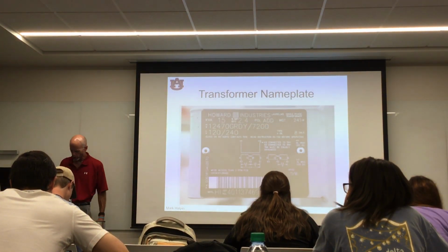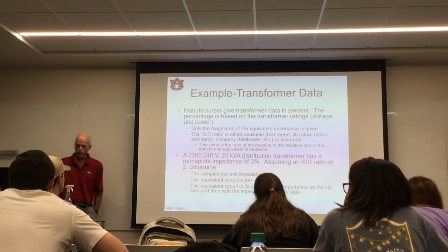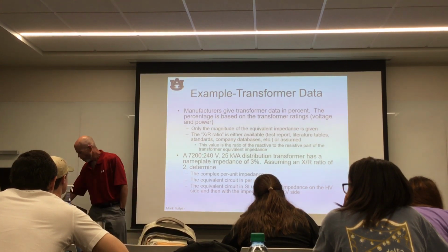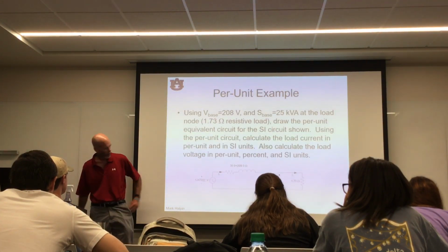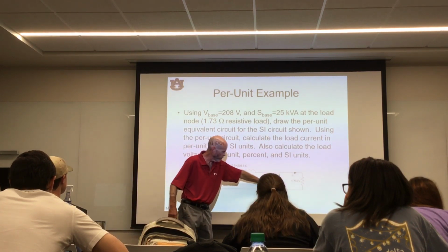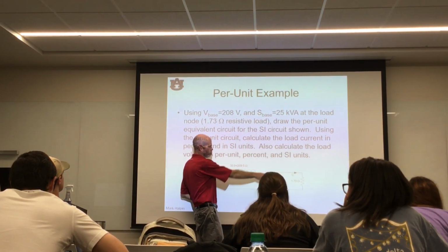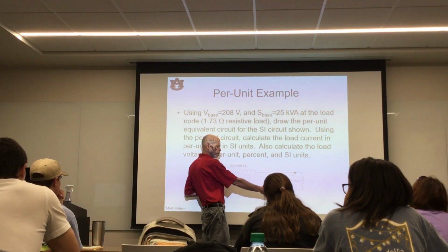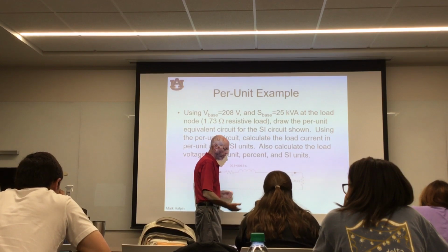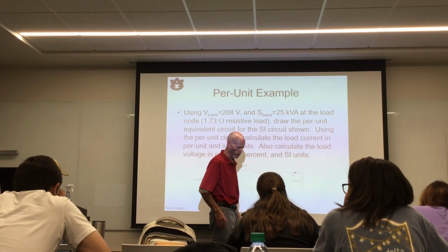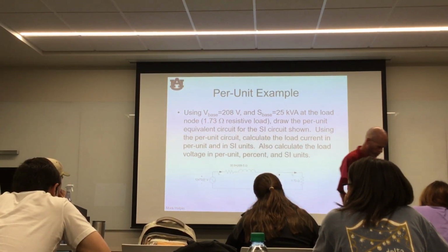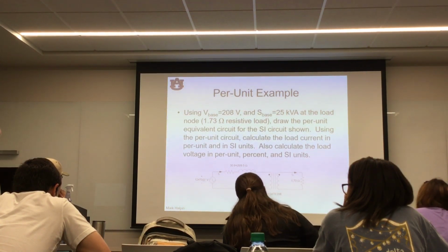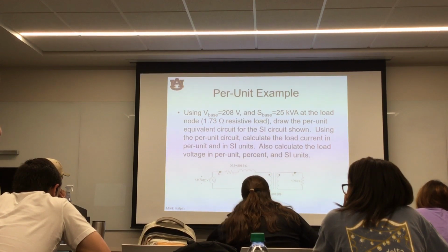So, manufacturer kind of saves us. But, transformer, okay, right here. Well, here's an impedance and a source and load. So now let's say that this transformer is that Howard Industries transformer. We got the nameplate. The manufacturer is telling us the percent impedance, right? But what did the nameplate say? It said percent impedance 2.4.